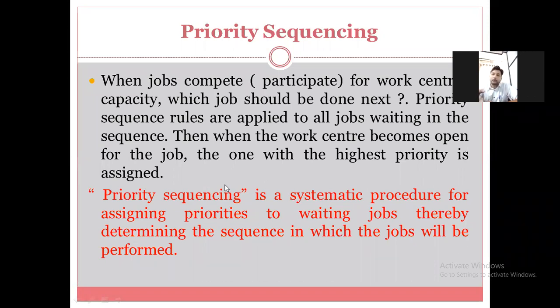Let us consider, first of all, you are doing the operation of installing the job. Then secondly you are doing facing, then turning, then drilling, then knurling. These operations should be performed in a sequential manner so that the time required, the material required and the processes will get optimum. Optimum means the required things are performed as they are.